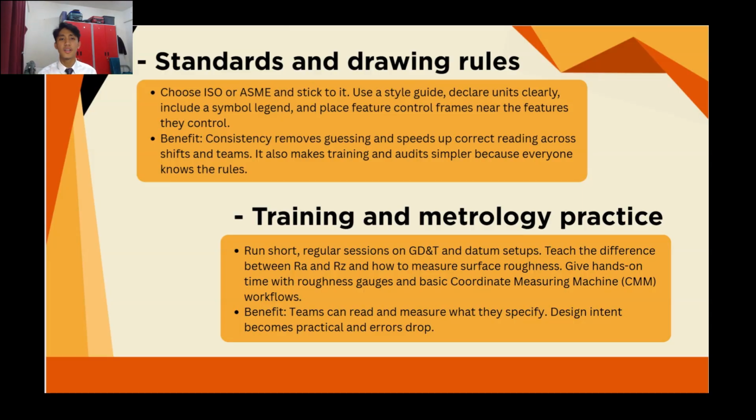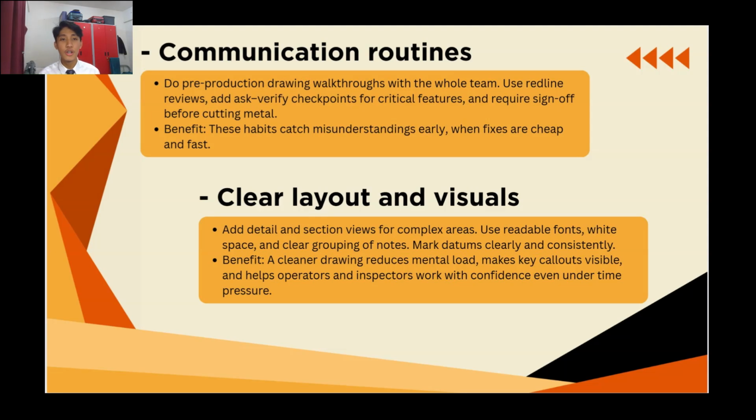The third one is communication routines. Do a pre-production drawing walkthrough with the whole team. Use red line reviews and add verified checkpoints for critical features, and require a sign-off before cutting metal. The benefit is that these habits catch misunderstandings early when fixes are cheap and fast.